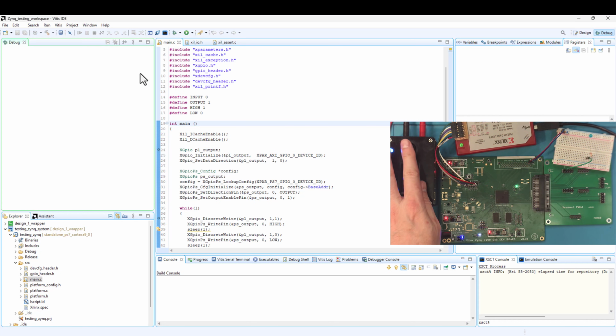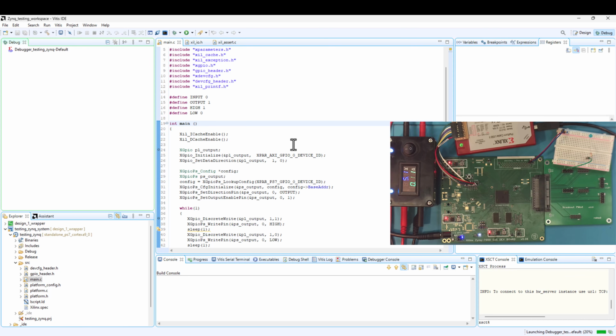Okay, with that, I'm going to go ahead and turn off power and turn my programming cable back on, turn my board on. It's not programmed because the done light is not on. I can also tell it's not doing a whole lot because of the power it's pulling. And then I'm going to come in here, and this time I'm going to go ahead and do a debug. And I can tell it's detecting that cable, so I might have run that a little bit too quickly, but we'll see if it gets my connection established now. So let me just try it one more time.